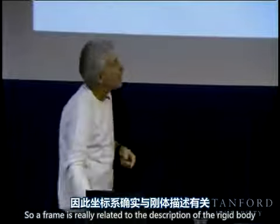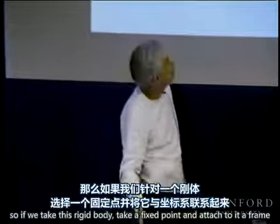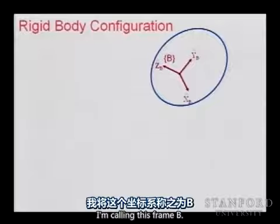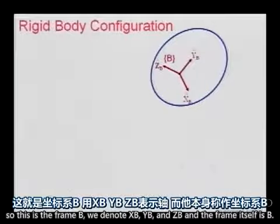So a frame is really related to the description of a rigid body. So if we take this rigid body, take a fixed point, and attach to it a frame, I'm calling this frame B. So the coordinates are going to be described with respect to those axes. So this is the frame B. We denote XB, YB, and ZB, and the frame itself is B.